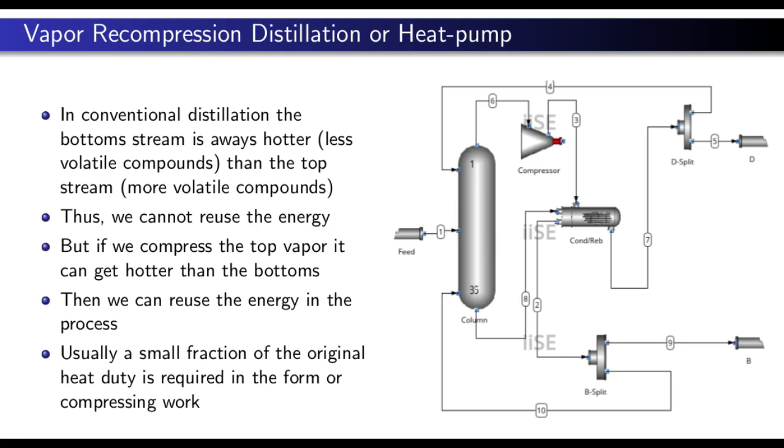What if we compress the top vapor? Maybe it can get hotter than the bottom stream. Then we can reuse that energy in this very clever way. The advantage is that now only a small fraction of the energy is required, but in the form of compressing work.